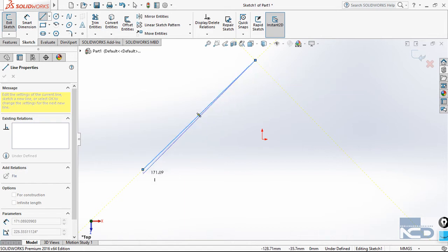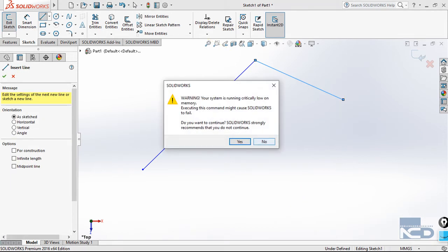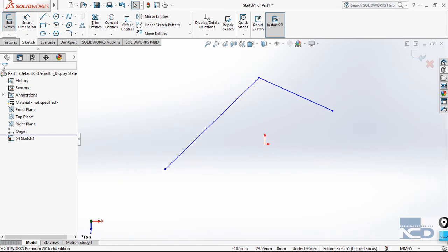Similarly over here, once the line is created it will create a new line again, and this time the end point of the first line acts as the starting point of the next line, and when we click anywhere again that line will be created. Similarly, you will find that again a new line is created from that endpoint. To stop this chain, we just have to press the escape button on our keyboard. Once you press escape, you come out of the line command and you will find that the object is now created.